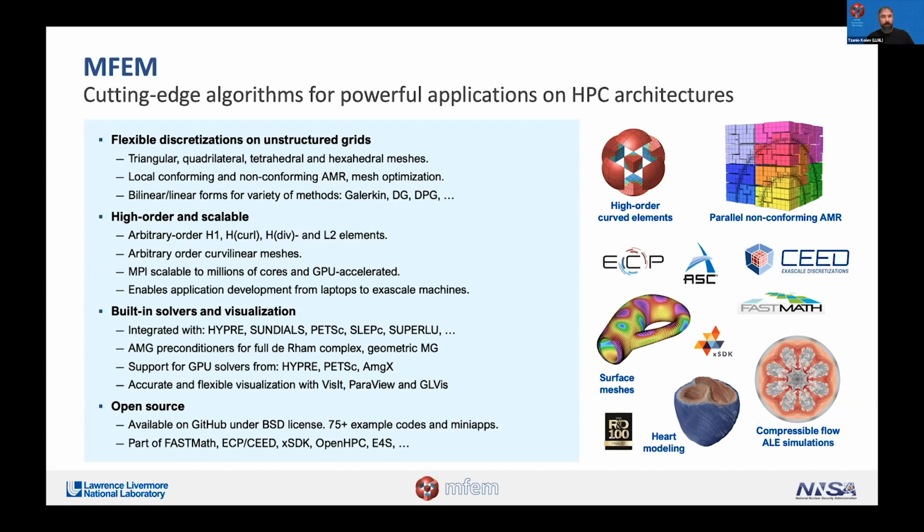We want to scale in the whole hardware spectrum, though. It is very feasible that you can start with a simple serial code in MFEM on your laptop, download it, build it without any dependencies in 10 minutes. And then as you progress with a small number of changes, you can turn it into a highly scalable code that you can run on a supercomputer. And then you can even use GPU acceleration. So it's really the whole spectrum.